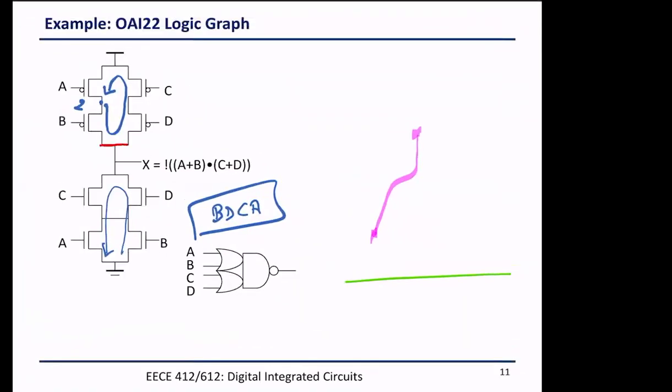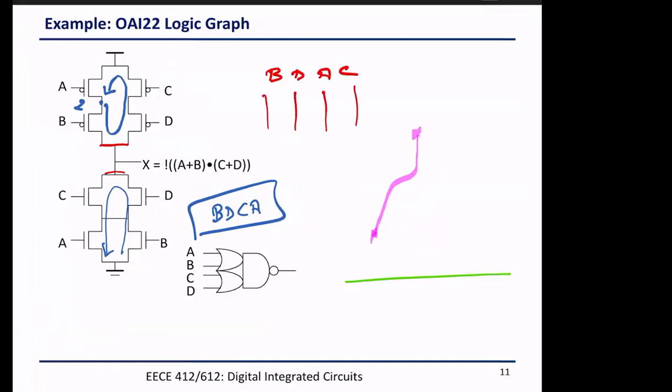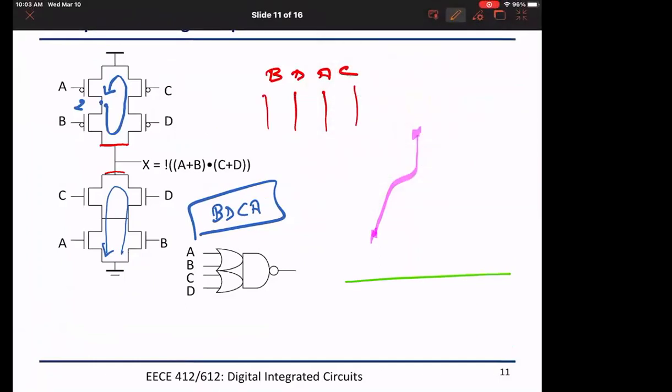this means that the capacitance of the output is not much, because it's a shared diffusion. What you can think of is that when I draw this loop here, for example, in this scenario, I have my poly, and if I look at the stretch of the PMOS, this stretch of the PMOS from node 2 to out to VDD to the intermediate node 3, then to VDD, then to 2.